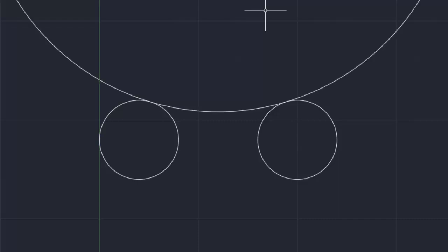So enter 6, enter. And you'll see the curve comes into that face first, that face second, and it goes that side. This is the problem that I have. If you put tan on here, it could equally pick it on the other side. Okay? You put tan on here, again, it could equally select that it would be a tangent on the other side. Okay? And if you don't do the conventions that the machine likes, one of these days what you're going to get is that circle will go on there with a 6-inch center, but it will be sitting that way over the top. So I like to encourage it to go in a positive direction and do my counter clockwise.